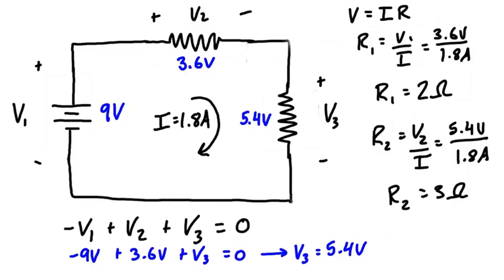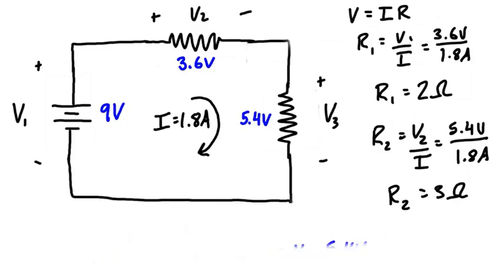So if we were to ground the bottom node, let's clear up some space down here, then we can write on the ground symbol, and this is going to set this entire node to our reference point of 0 volts. Let's identify all of the nodes that we have. We're going to have this node that's grounded, which is everything until we hit the other elements. We're going to have a node up here, and then one other node over here. Because the blue node is grounded, we're declaring that one to be our reference of 0 volts.